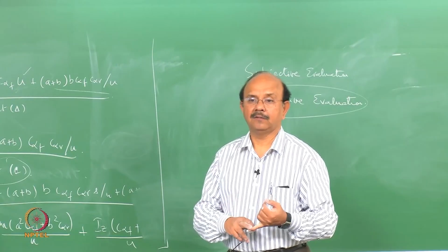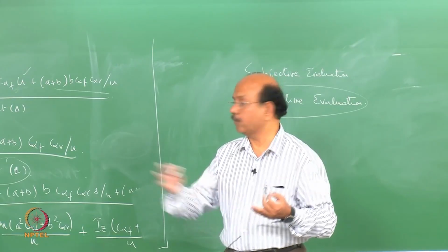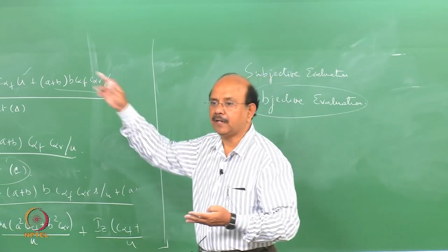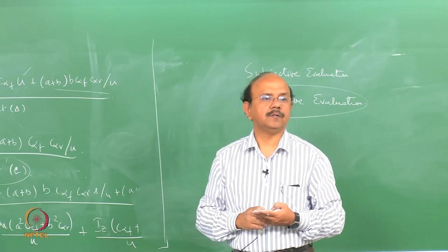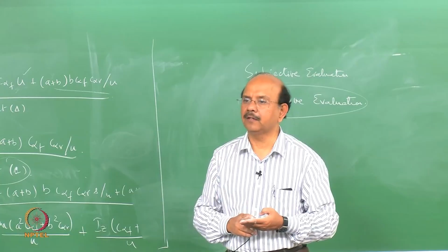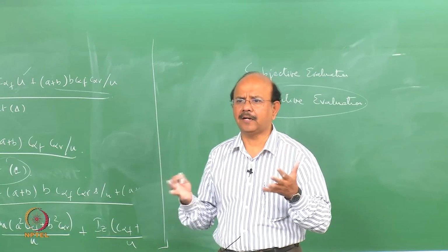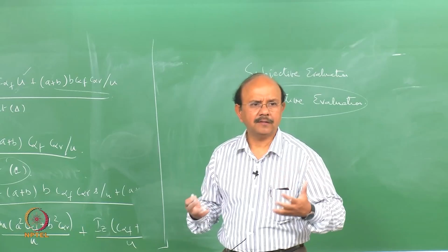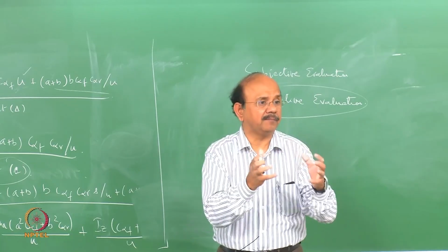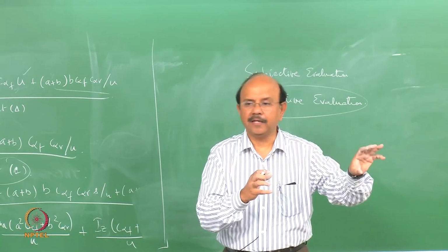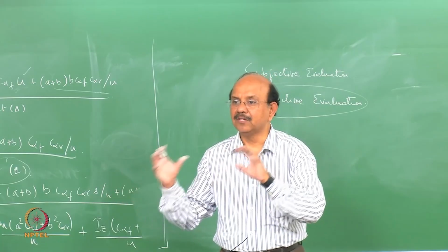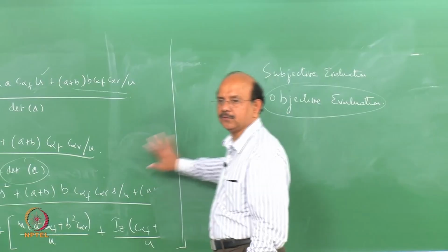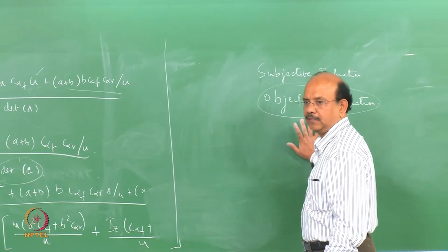I have a yaw, I have a yaw rate, I have some yaw rate gain, I have lateral acceleration, I have beta, V by U, the vehicle slip angle, and so on. So many things that now I know what is important, how am I going to combine them and tell that vehicle A is better than vehicle B or vehicle C? In other words, how am I going to convert these things into characteristics of the vehicle? That's what we will see.